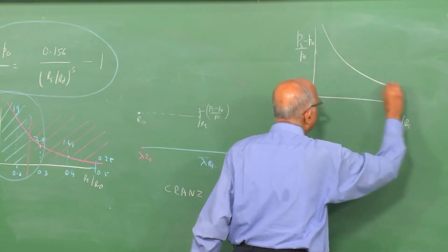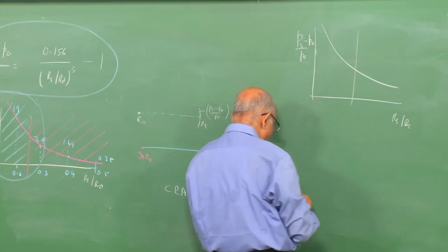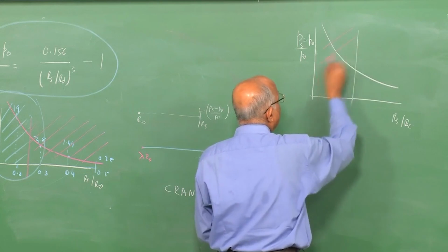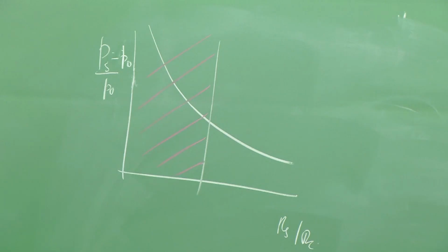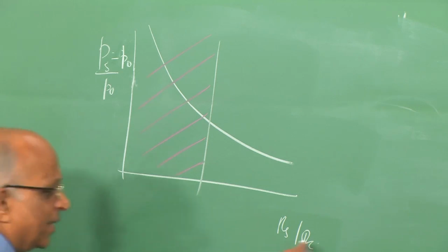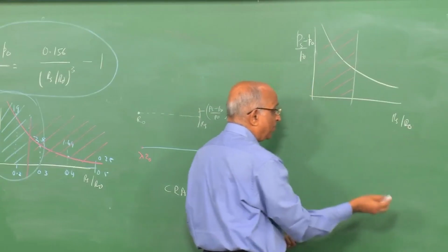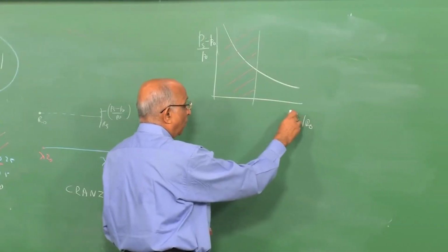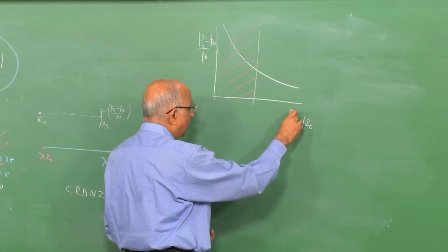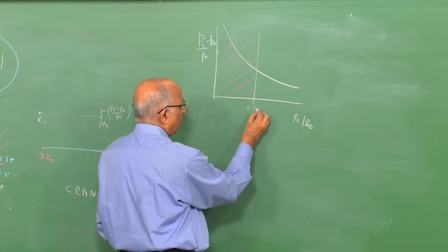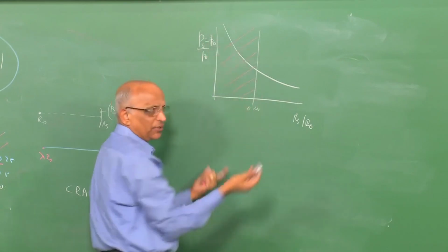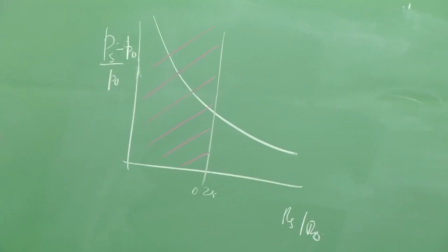We got this particular curve. We said our curve is valid only in the near region of the blast, in which the blast wave is strong. And now, once I know the energy release from the explosion and the ambient pressure, I can calculate R0. I want to calculate the overpressure at a given distance. If the distance falls within this, which is let us say around 0.25 or so, I can predict my overpressure, and we are able to do some problems now.